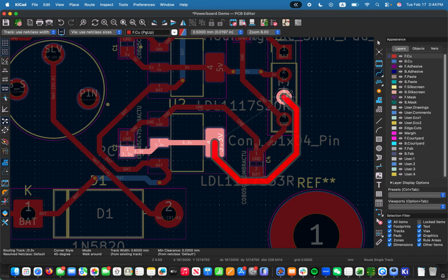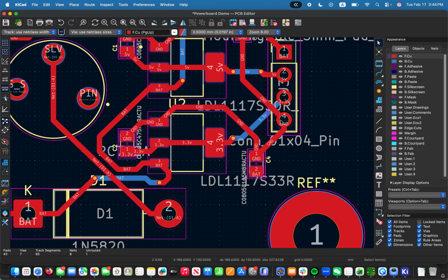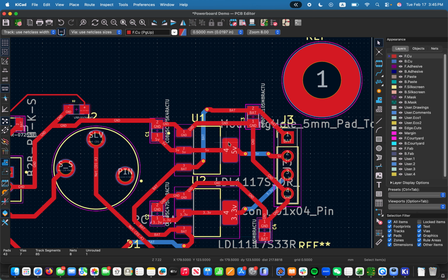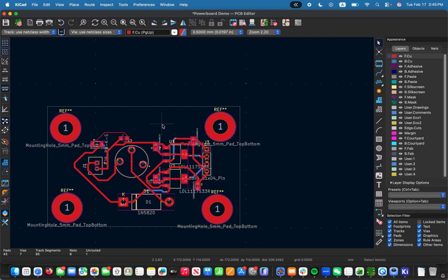And for simplicity, I'm just gonna go trace around because I don't want to place a via and then another via to come back. Actually, if I place a via here, since this is a through hole, I do not need a second via to come back to the red layer. Let me just demonstrate that. So let's place a via right here. So now we can directly connect through, because imagine the red is your overground bus lines and the blue is your underground subway. So you can route blue under red with no problems. So now just looking around for a sanity check, making sure that there is nothing else not connected. Let's press save, and let's view our 3D viewer.